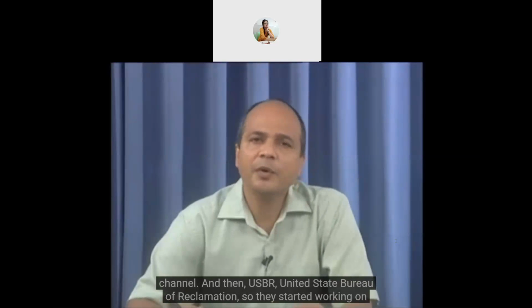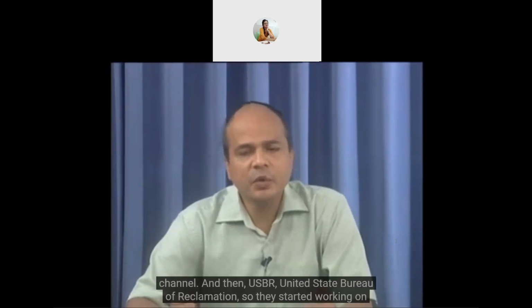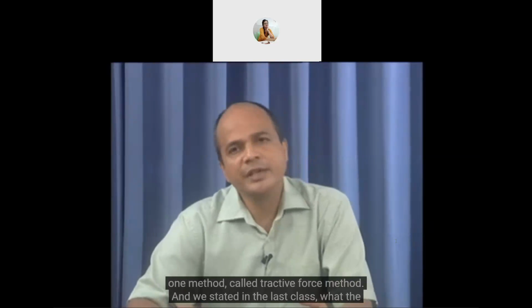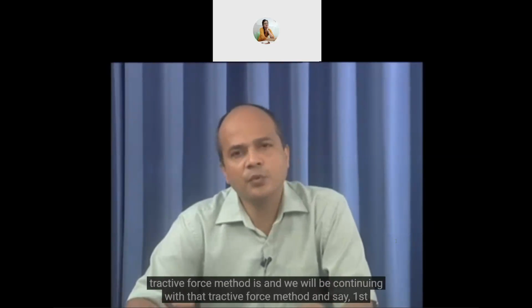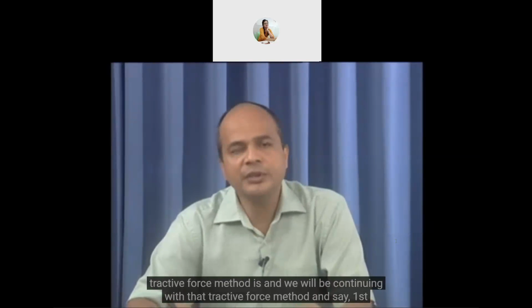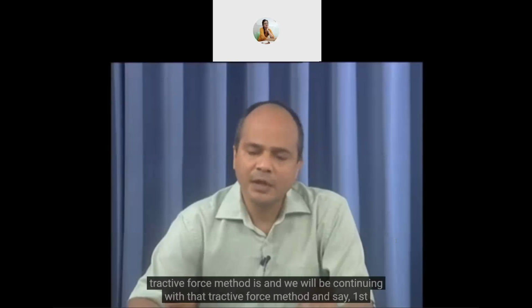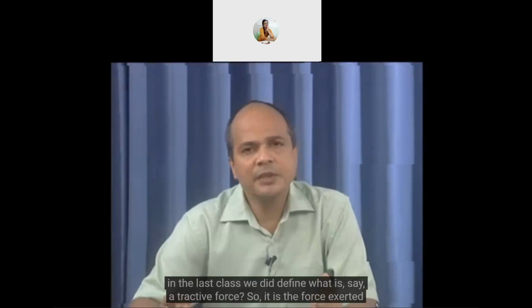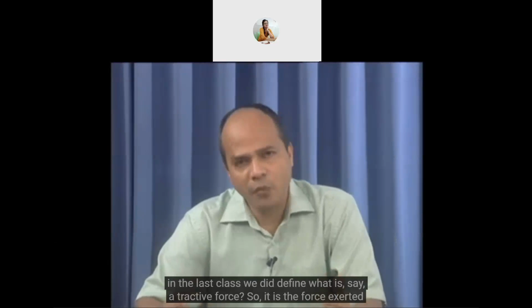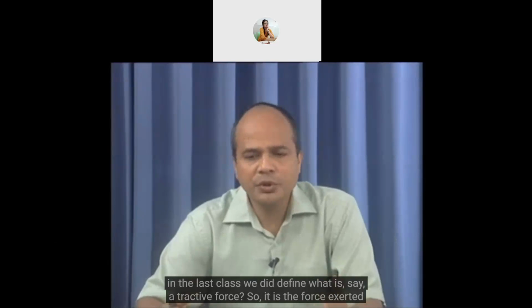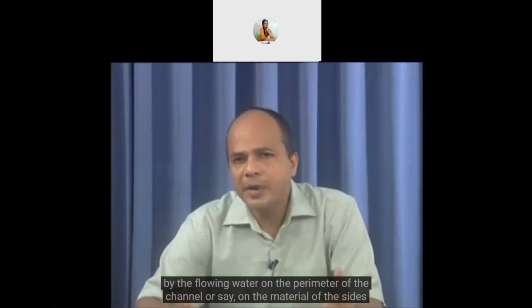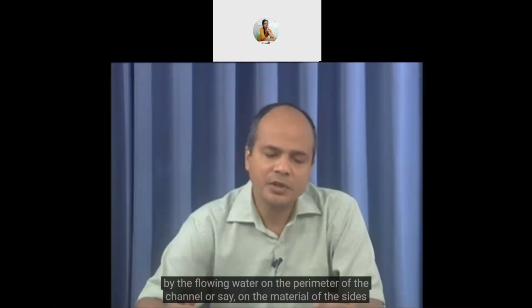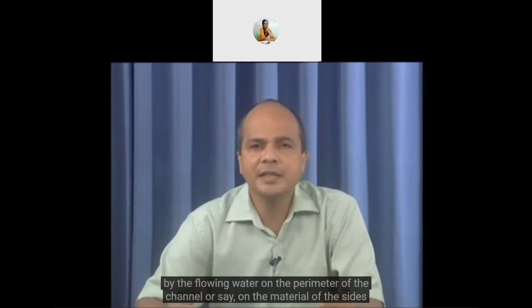Then USBR, the United States Bureau of Reclamation, started working on one method called the tractive force method. We started in the last class with what the tractive force method is, and we'll be continuing with that. First, in the last class we defined what tractive force is: it is the force exerted by the flowing water on the perimeter of the channel, or on the material of the sides and bed.